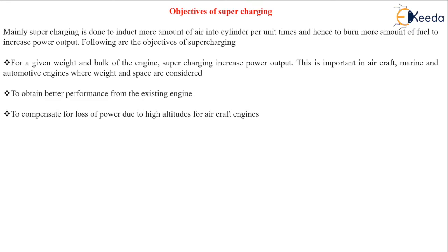You have to consider the weight of the engine and the space in which it is to be accommodated, and at the same time you have to work towards increasing the power output. So by keeping a check on the weight and the space of the engine which is allowed, supercharging, that is compressing the air or the air fuel mixture before delivering to the combustion chamber, might lead towards increased power output.